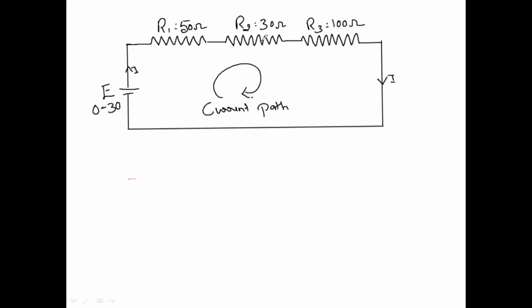Okay, and we know the resistance values also, so we can directly go ahead with the equation. Sum of the voltage drop is equal to sum of voltage rise, that is equal to 0. So this will become 50 into I, that is I into R, minus, because a resistance opposes, the direction of current and the circuit diagram current both are in the same direction, so it will be considered as a negative sign.